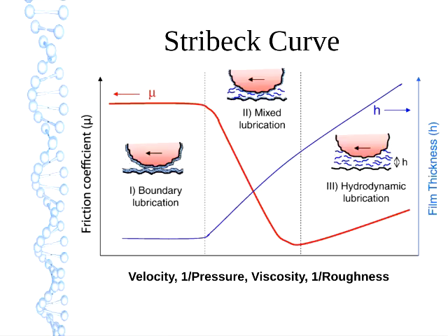So as we start off on the left, you have boundary lubrication. Here the surfaces are actually touching. They are separated by a molecular film which covers their surface, or by some solid additives, but with some minor materials interposing themselves, the asperities are touching each other.